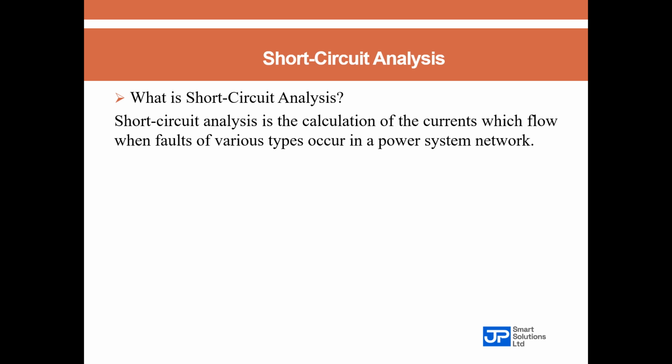So on power systems, we have various types of faults which we can classify into symmetrical faults and asymmetrical faults. So basically symmetrical faults are for three-phase faults, that is a fault involving all three phases or all three phases and ground. While asymmetrical faults are examples like line to ground, line to line, double line to ground faults.